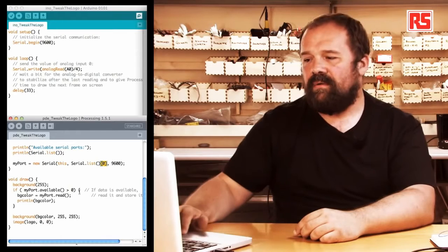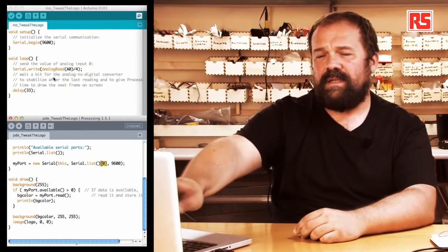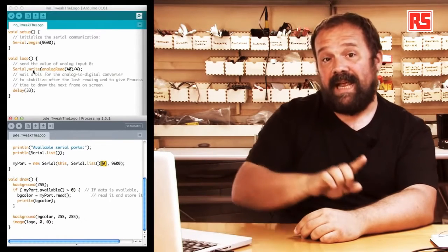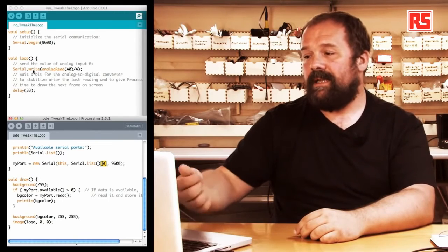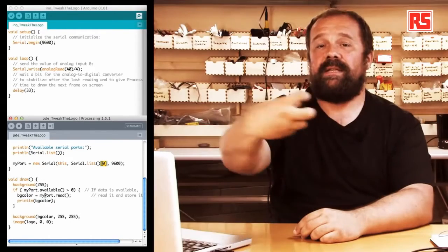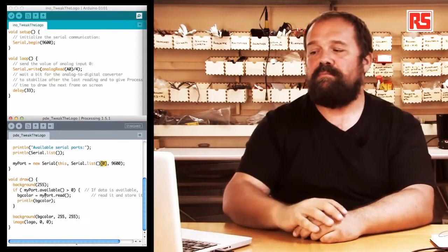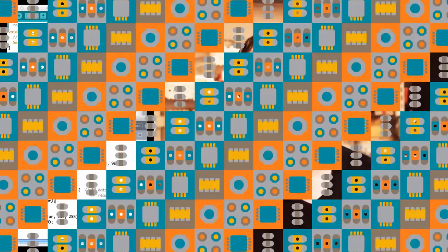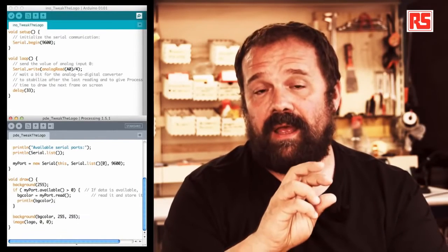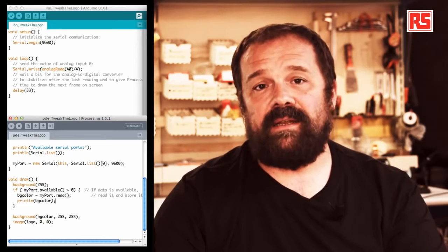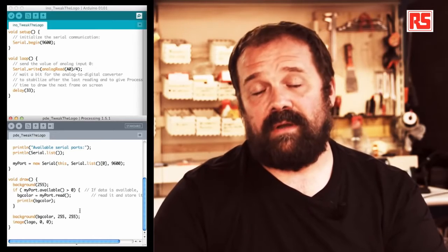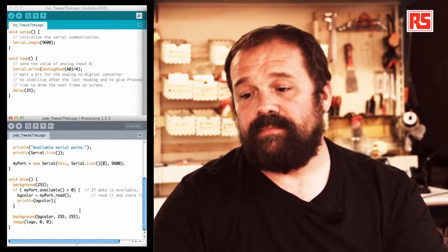So you can see now, by looking at the code side by side, that on the Arduino side we have Serial.write that sends the data. And then on the Processing side, we have myPort.read that reads the same number into the bgColor variable. After reading the value that comes from the Arduino into the bgColor variable, we use println(bgColor) to print the value contained inside bgColor at the bottom of the Processing IDE window.